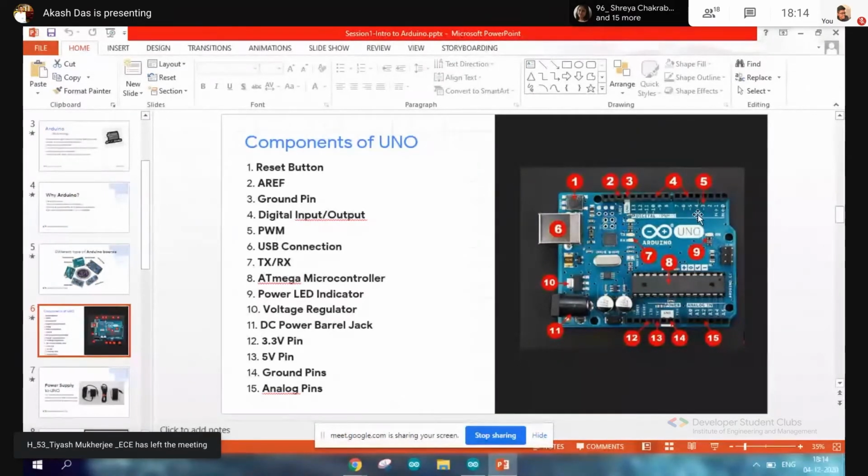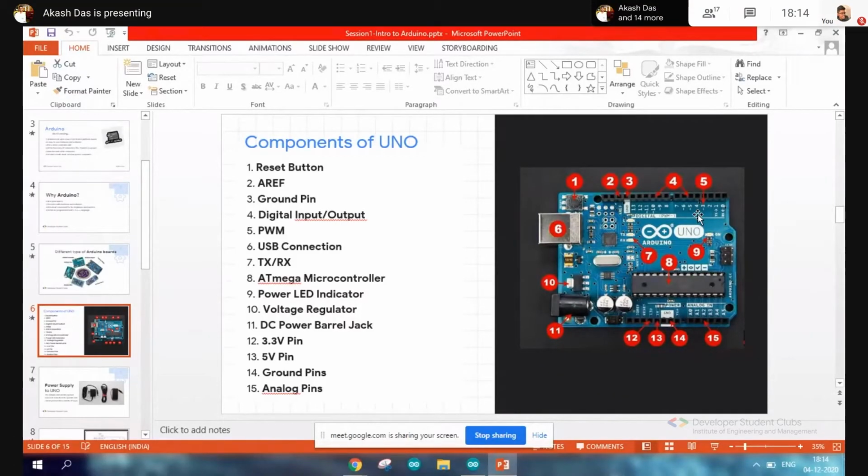Arduino doesn't have any digital to analog converter. So it uses these PWM pins to convert the digital values to analog values, by changing the sequence and the frequency of the outputs.